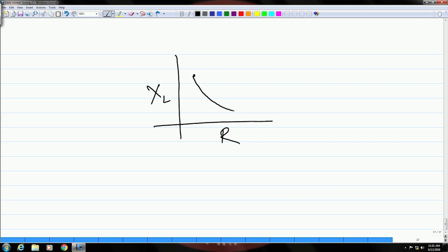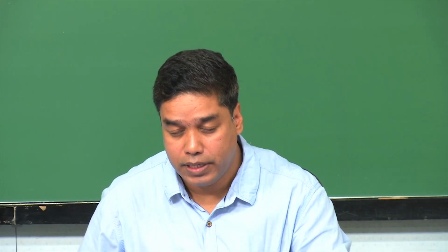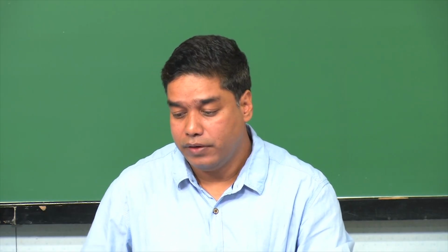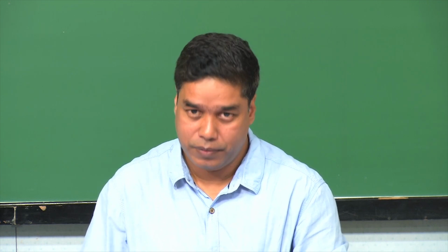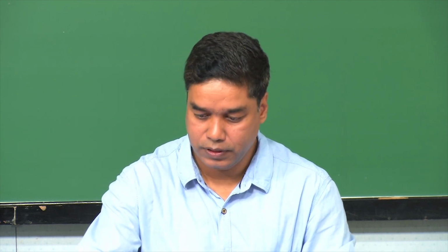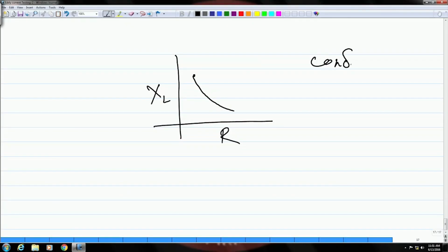Okay, so, this is the lift off. Now, this lift off curve, as to how far this resistance will increase and the inductance will decrease, will depend on the sample properties, particularly the conductivity of the sample.